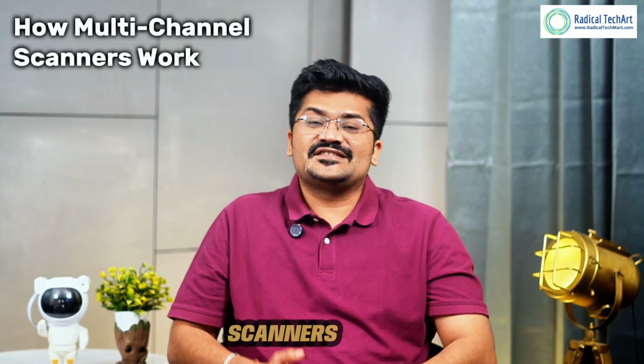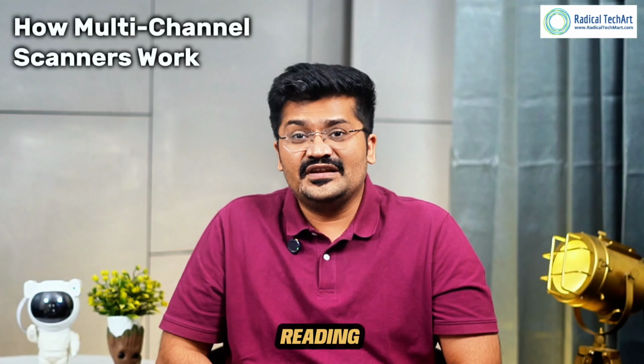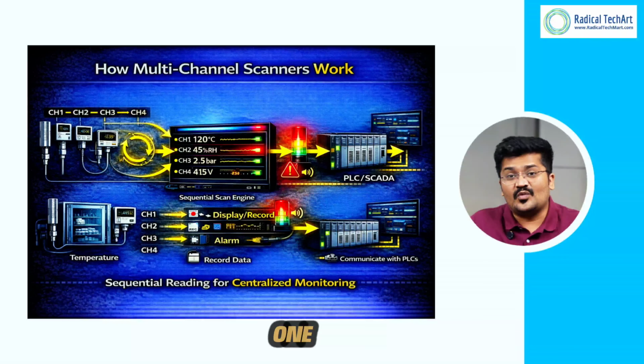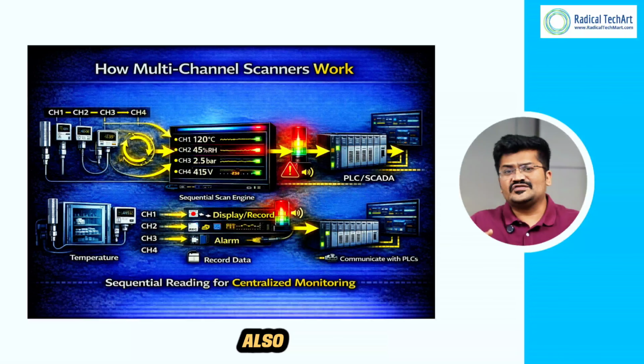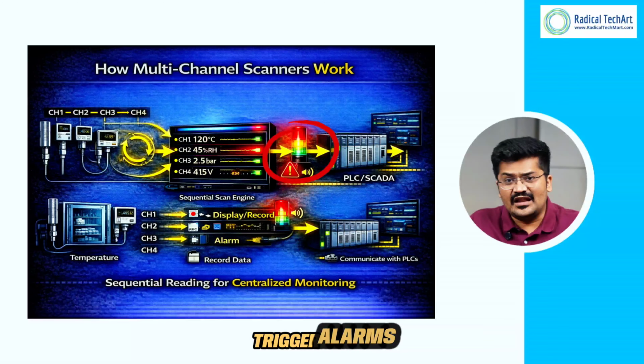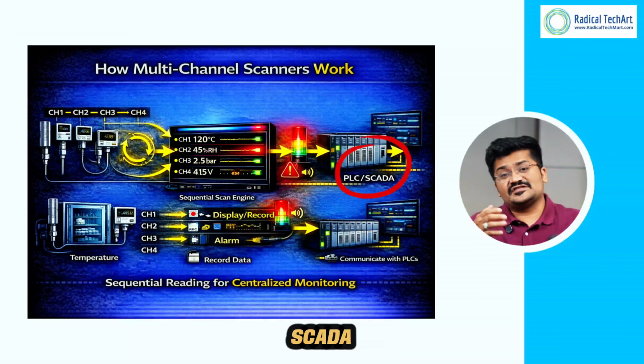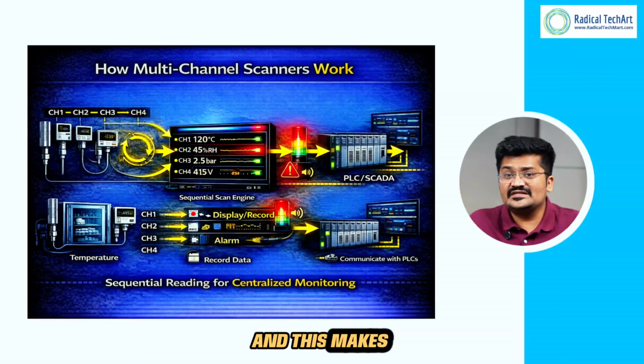Now, multi-channel scanners work by sequentially reading signals from multiple sensors. The device scans each sensor one by one and displays the value on the screen. Some scanners also record data, trigger alarms, communicate with PLC or SCADA system, and this makes them very useful for centralized monitoring.